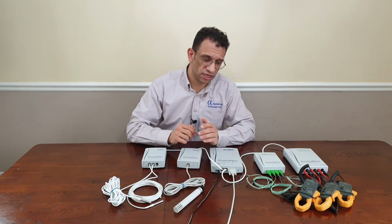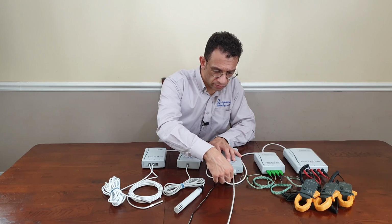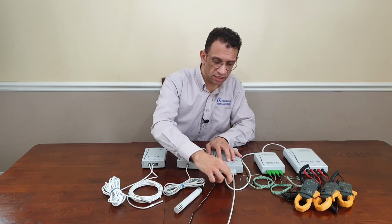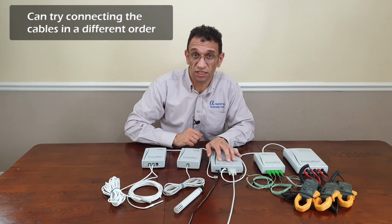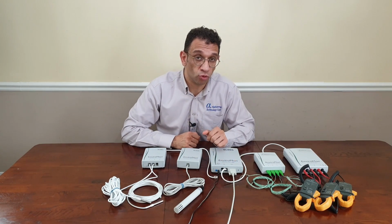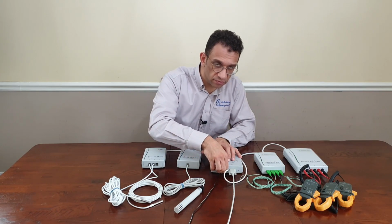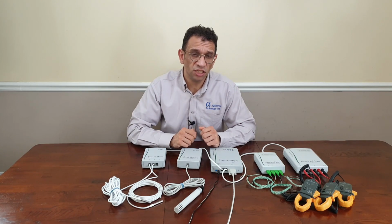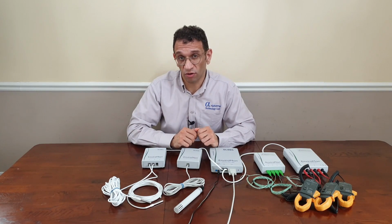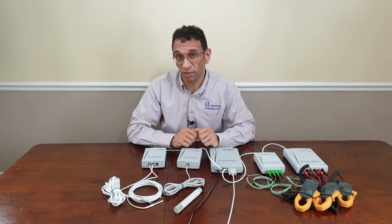Now you may want to try disconnecting both converter cables again, and then just connecting the second converter cable first. It doesn't really matter which way around you connect to the data logger, as both ports are interchangeable. And then connect the other converter cable. Sometimes it's worth doing them in a different order. Now this usually fixes most of the glitch problems you get with the logger, but it could be the case that only some of the converters have appeared or none of them have appeared. In that case, we'll try something different.